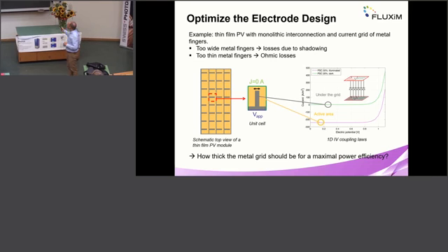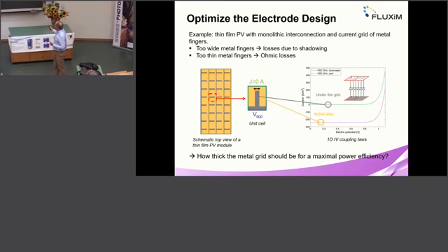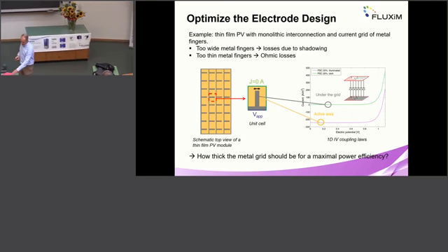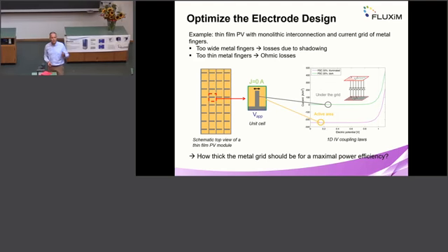So on the one hand, below the metal, we have to use a dark JV, which is this green line. So we have 0 current there, only injection in forward bias. And in the active area, we need to feed an illuminated JV curve. So that's the current divided by the area. That's input to the software. Why is this input? This sketch here I will explain later on. That's how the model is made. It needs an input law for the current density, how it depends on the voltage drop vertically between the two electrodes.